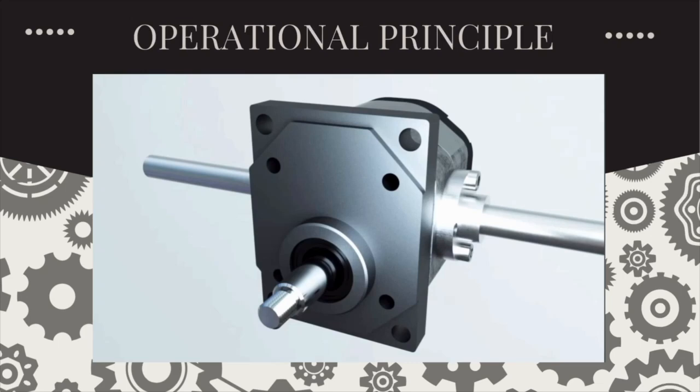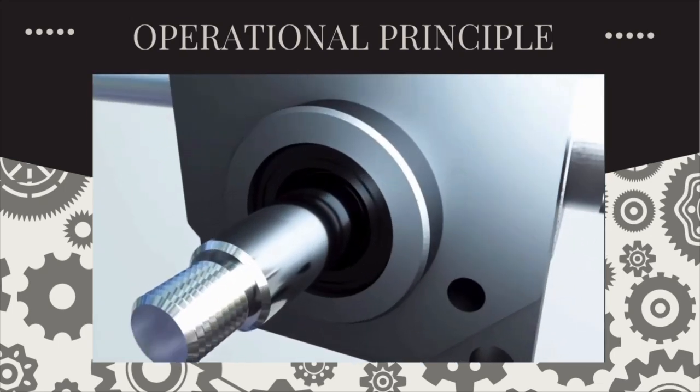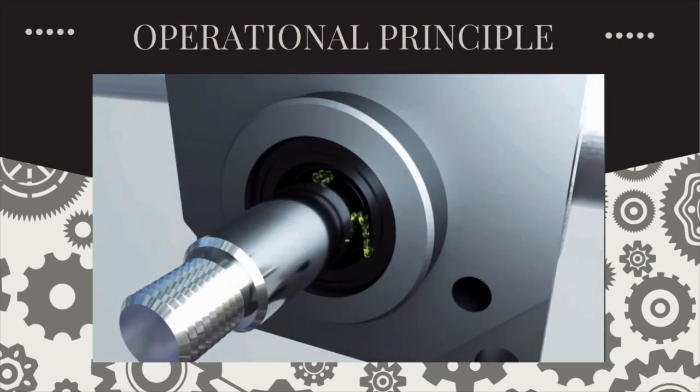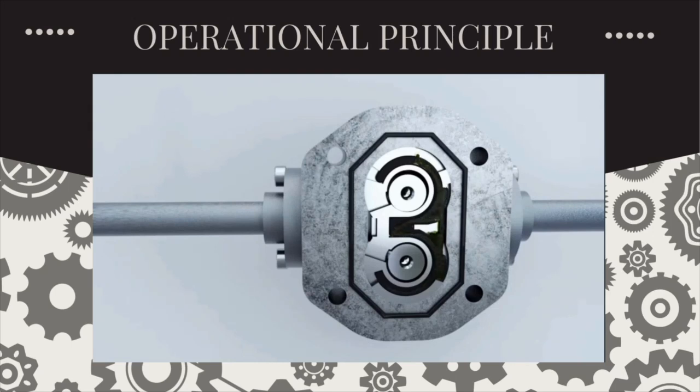Shaft sleeve wear. Oil will flow out through a damaged shaft sleeve. If the seals become damaged, fluid may begin to flow from the discharge area to the suction area. This will cause a reduction in the working pressure and supply. So this is how a gear pump works.